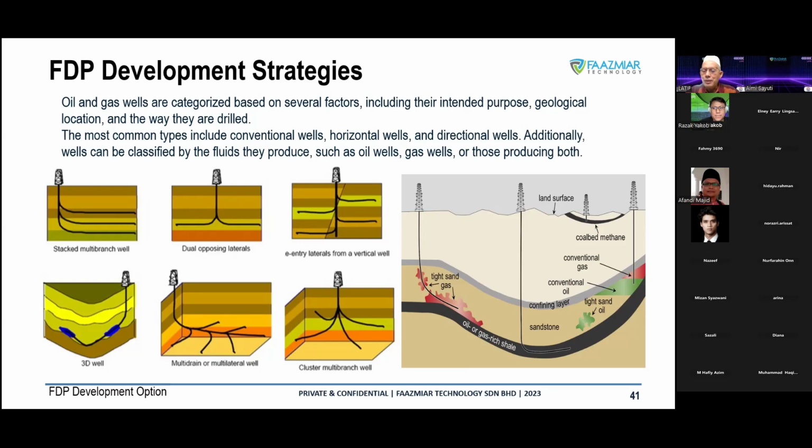Even now, we are also having a service provision to do fully automated drilling. For example, you set a target, and then the computer system will more or less direct the RSS to drill to the target without any human intervention. You just set up the target on the computer, and it will adjust itself based on the current profile, follow the profile and hit the target in automation mode.